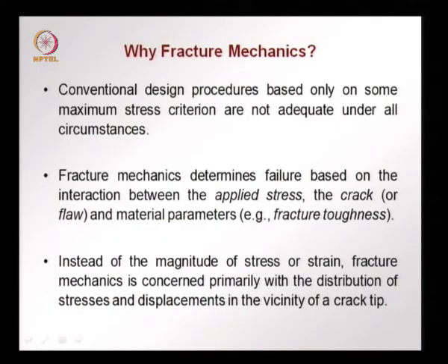So, why fracture mechanics? What is different about fracture mechanics? Conventional design procedures that are based on the maximum stress criterion are not always adequate. Failure theories and concepts that we discussed in the previous 2 lectures always consider a material free of defects and free of discontinuities. Fracture mechanics now determines failure based not only on the applied stress, but also on the crack or the flaw that is present, and brings in new material parameters like fracture toughness instead of just the stress or the strain limit.